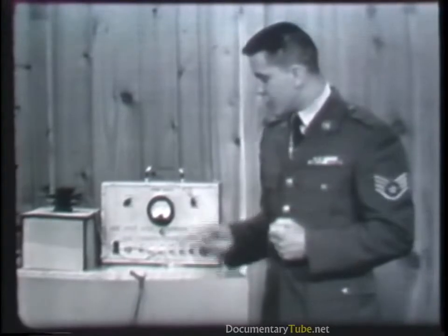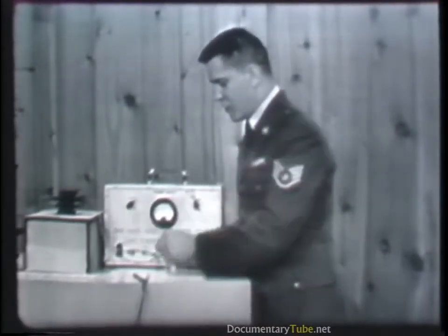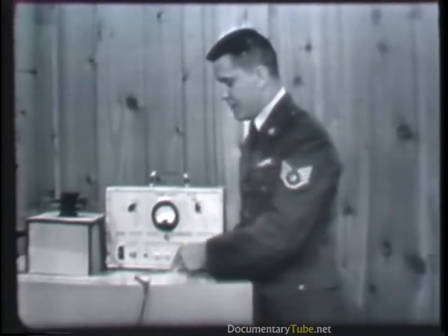Well, let's measure the resistance of the windings in the transformer we're using here and see if this holds true. Before we do it, however, there's a few words of caution I should point out, and that is, whenever making resistance checks in a transformer, ensure there is no voltage applied to the transformer. So let's turn the voltage off, disconnect the lead so we'll get accurate readings on our transformer windings, and let's proceed with the checks.